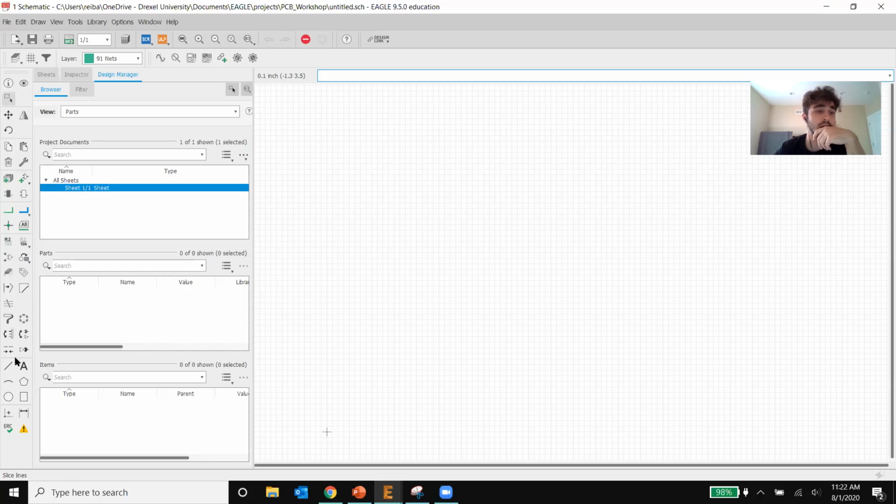So let's start. Here on the left, I'm sorry, you have all these commands. Here you have adding parts. This is moving, mirroring, and rotating. Here you have deleting, changing, copy paste. Here you have adding parts, adding design blocks, adding modules. This is adding nets and junctions, all those sort of cool stuff. Name, value, reposition attributes, replace. We're going to understand what these things are as we go over.